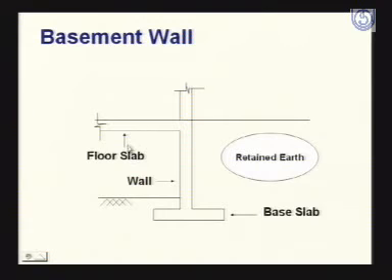And you are constructing the basement of the building, so just to retain the level difference, because this is the high level, and because of this basement you have excavated your plot. Because of this level difference, you will require a retaining wall, and this wall is called the basement wall.